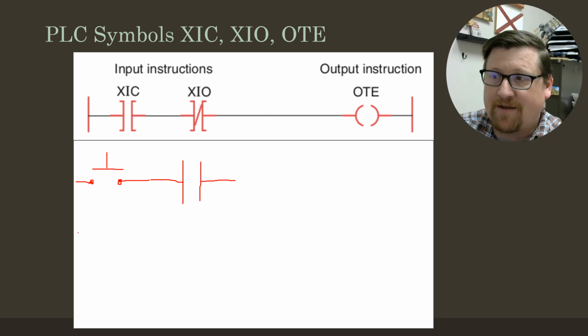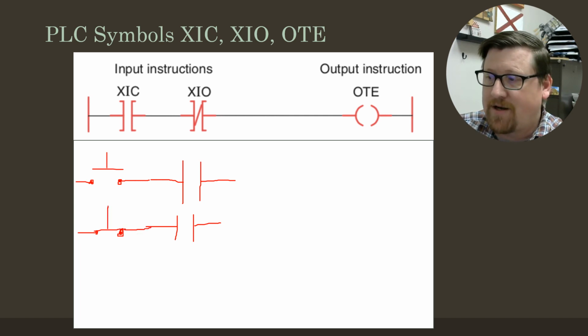But if this examine if closed bit inside of the PLC is hooked to a normally closed contact, right? Now it's going to light up all the time, right? It's going to be true, unless somebody pushes that push button and opens it, right?